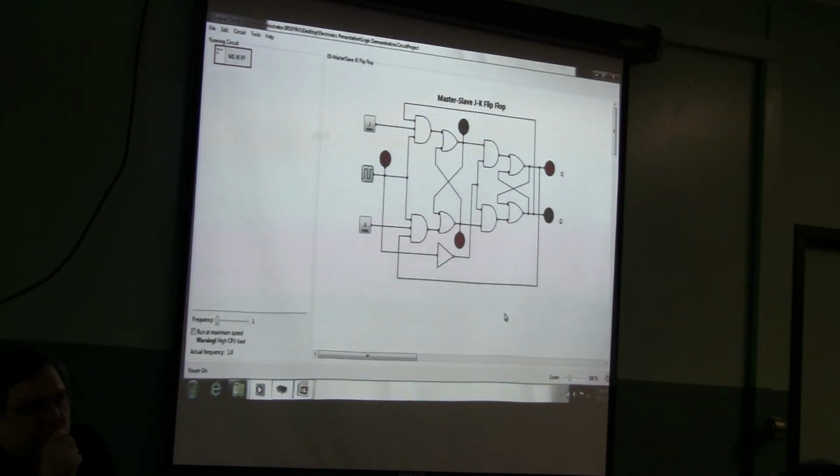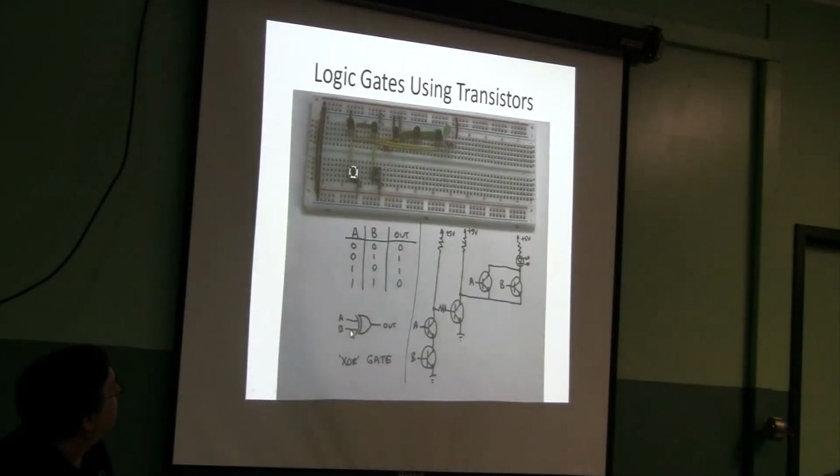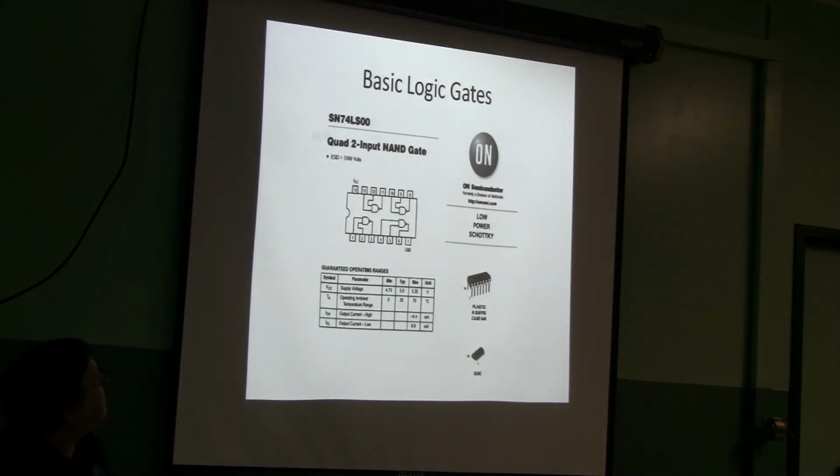I was wondering about the prefix on the first or second slide that you had, SN74LS00. I think that's a manufacturer prefix, National Semiconductor's or TI's. The important part is the 74 and the numbers. Ignore the letters; that tells you what kind of gates they are, what kind of circuit it is. The other letters in the characters tell you how the circuitry is built. What types of transistors are used?